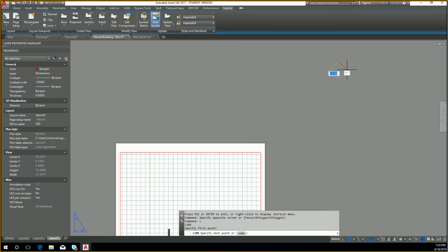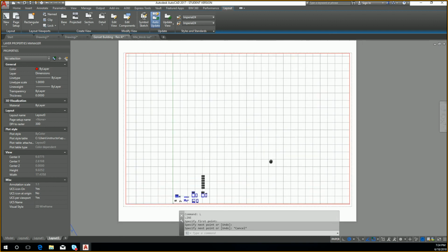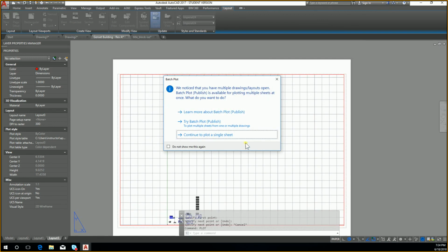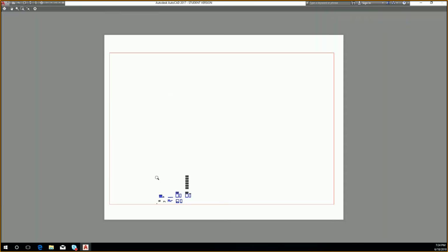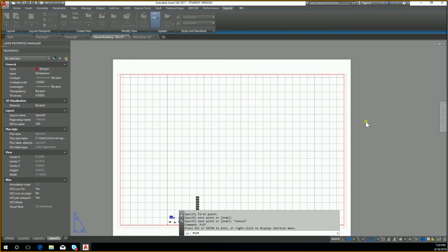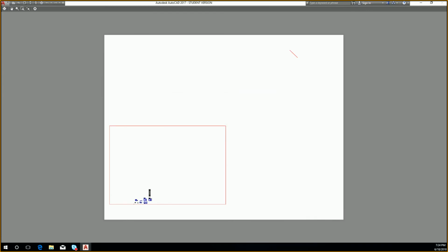So this also means within paper space. Back to extents. Within your paper space, it will also print to that maximum extents. So it will help you catch any mistakes or things that are drawn in by accident. Extents is a nice way to check that sometimes.